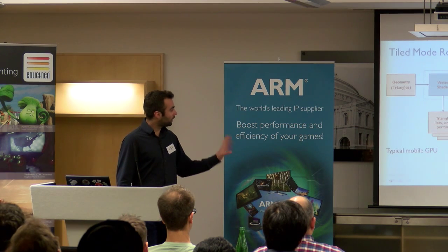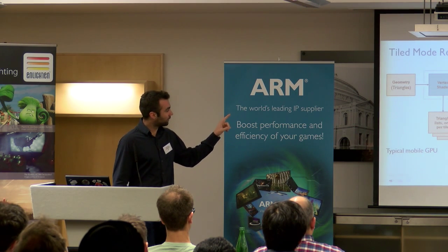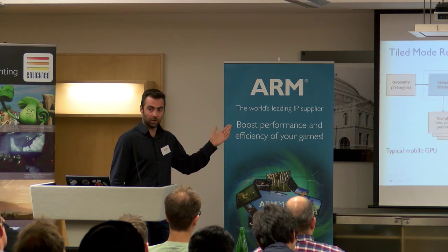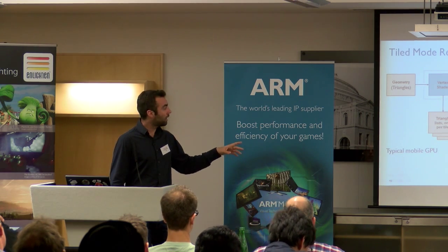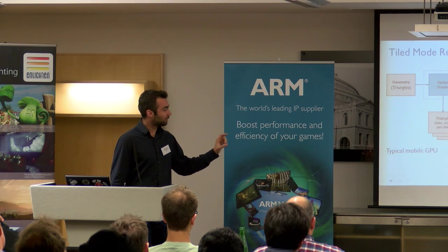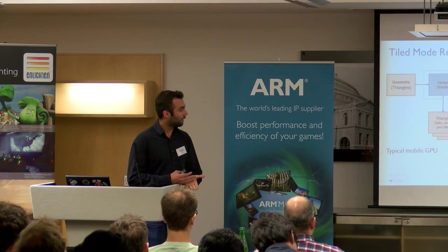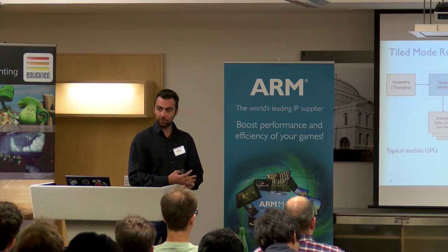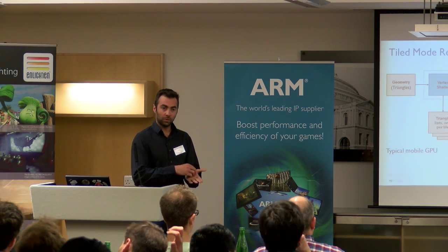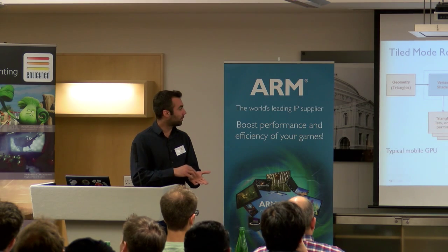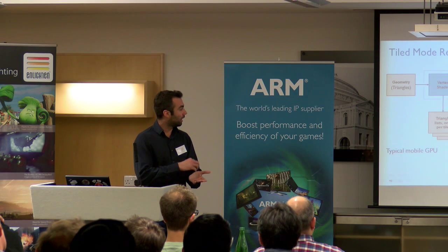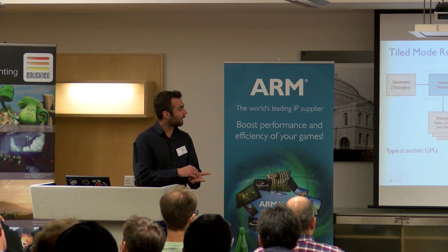So the only overhead in this case is that after doing the vertex shading, you have to store the pre-processed geometry in external memory, along with the triangle list, one per tile, which is going to be provided to the next stage of processing, in pixel processing, in order to do the process on a tile-per-tile basis, and in order to make sure that you will only read the relevant geometry for this tile.